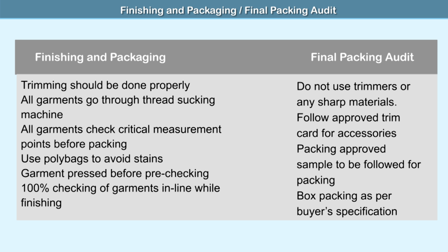Trimming should be done properly. All garments go through thread sucking machine. All garments check critical measurement points before packing. Use poly bags to avoid stains.